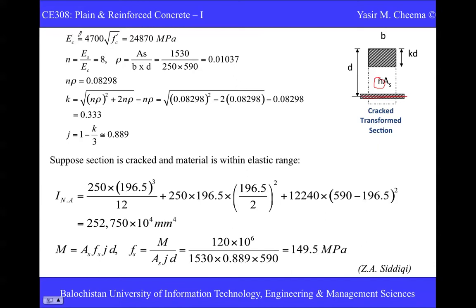For the modulus of concrete you can use this formula, because every concrete's compressive strength varies from site to site, so it is better to use this formula. Fc prime, the compressive strength, is given to you in the question, so using this formula and Fc prime here you can find out the modulus of elasticity of concrete.